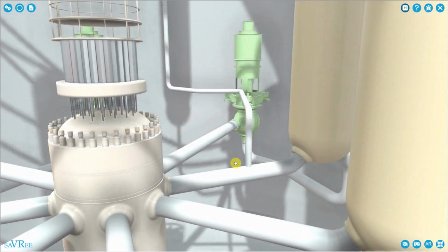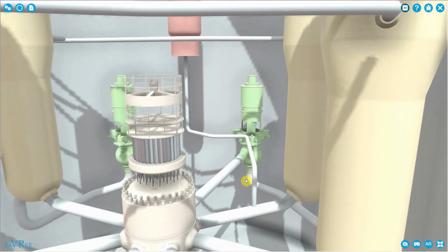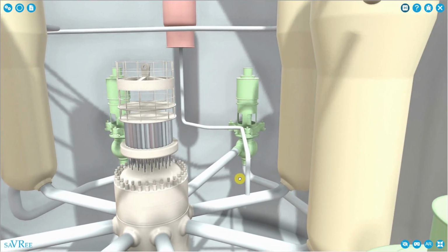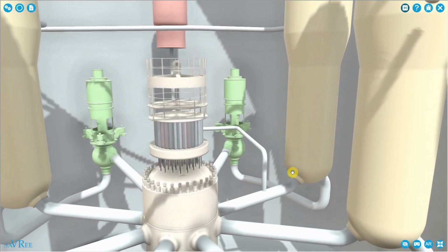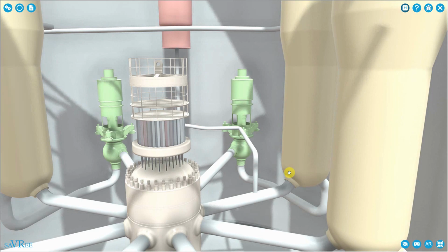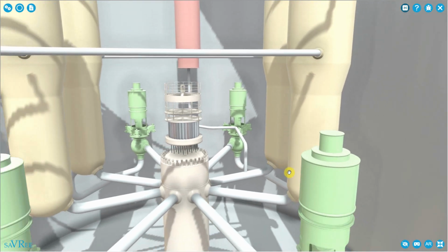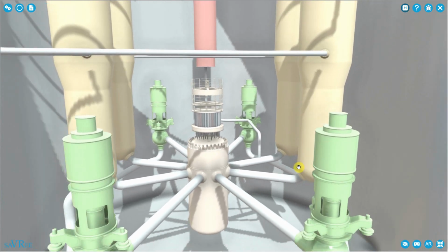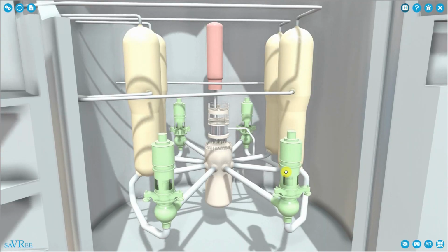So we've got the pressurizer, which is maintaining the primary coolant under pressure. It's preventing the primary coolant turning to steam. When we pass the coolant through the steam generator, it's going to give up some of that heat to the secondary cooling circuit, the secondary coolant. Let's have a look at all of these parts now in a little bit more detail, because it's a bit easier then to explain what each of them does.